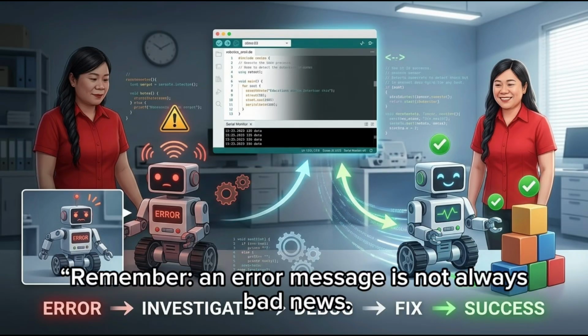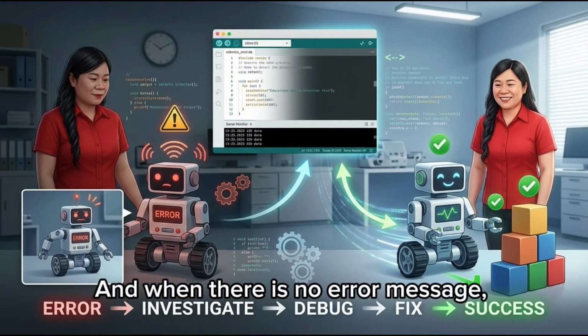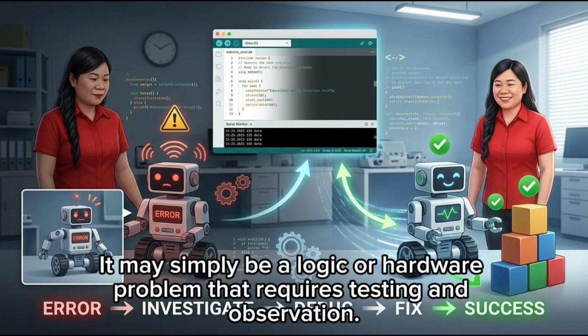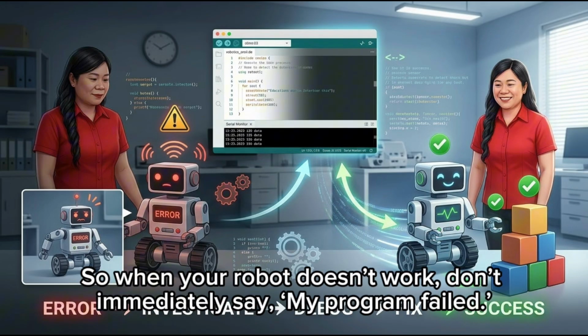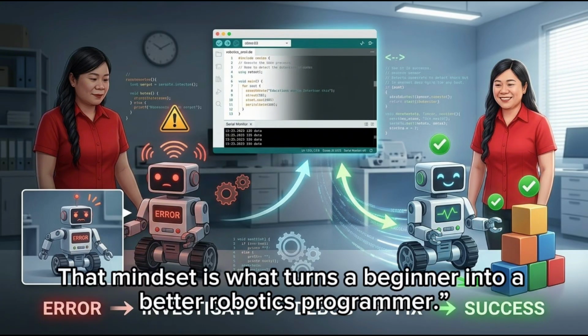The important lesson. Remember, an error message is not always bad news. Sometimes it is the IDE telling us exactly where to look. And when there is no error message, but the robot behaves incorrectly, that doesn't mean there is no problem. It may simply be a logic or hardware problem that requires testing and observation. So when your robot doesn't work, don't immediately say, "My program failed." Ask instead, where did the problem begin? Was it the code? The compilation? The upload? The connection? The power? The sensor? The actuator? Or the logic? That mindset is what turns a beginner into a better robotics programmer.